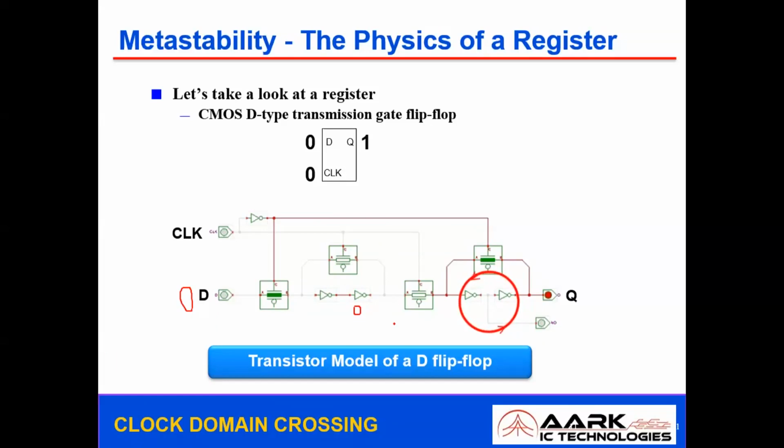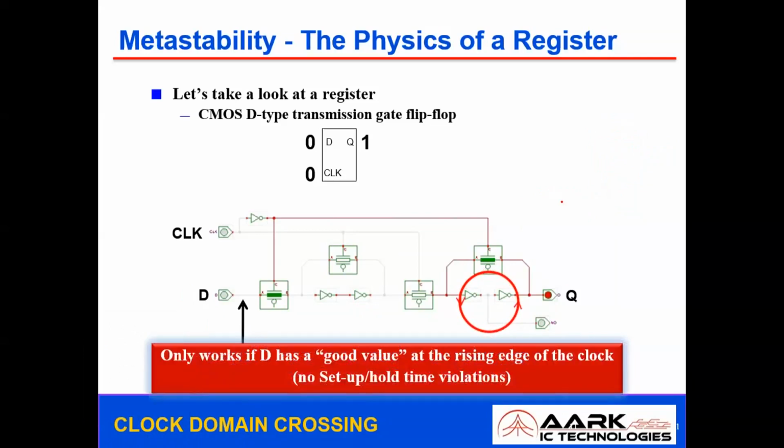So this is where the capturing is very important, and holding the data for this duration is very important. And this time we generally call the timing window. So during the rising edge and the falling edge, just before the clock edge, we should maintain the data stable, and even right after the passage the data needs to be maintained constant. So this is called a clocking window. If the data is stable during this clocking window, then definitely you can avoid the setup and hold violations, which can avoid the metastability issues.